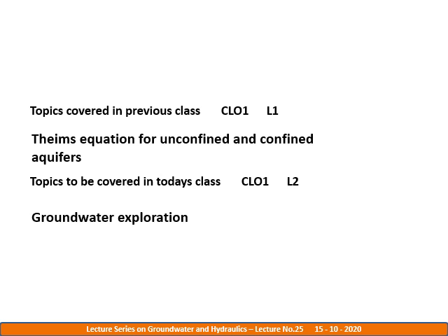The following information can be derived from exploration using geophysical methods: depth of aquifers and thickness of the aquifer. Second, declination of aquifer boundary of a very large groundwater basin. Third, quantity of groundwater and the spread of the pollution zones.